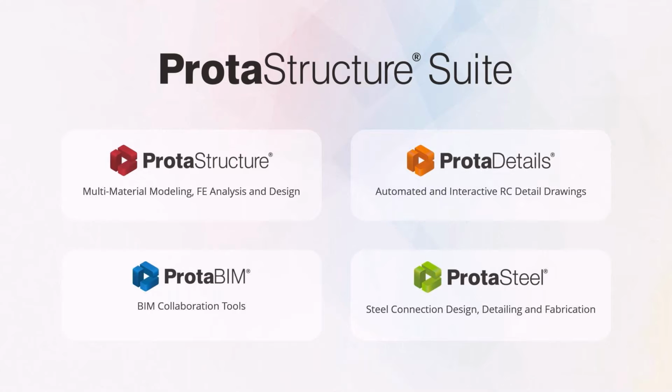ProtaStructure Suite consists of 4 different softwares. First one is ProtaStructure, where you can model and run finite element analysis. You can design your members according to the selected code. Then you can send your model to the ProtaDetails environment to obtain the reinforced concrete detail drawings. Or if you have steel members, you can send them to ProtaSteel and create your steel connections. You can obtain fabrication details and bill of quantity as well.